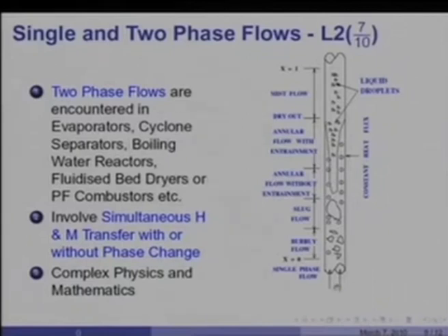So, essentially then you have flow with phase transition from liquid water to complete vapor, but in between there are regions of two phases, water and water vapor. In the bubbly flow, the dense phase, the water phase, dominates over the vapor phase.